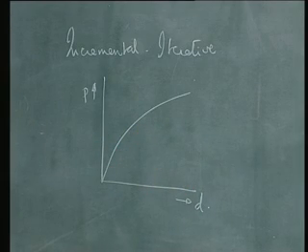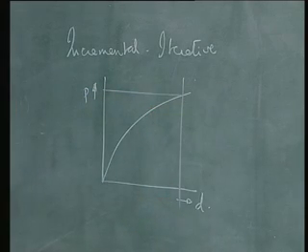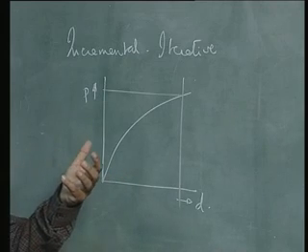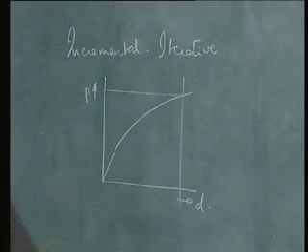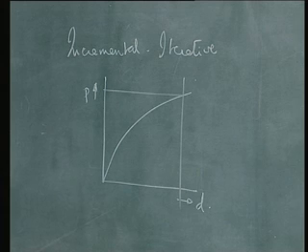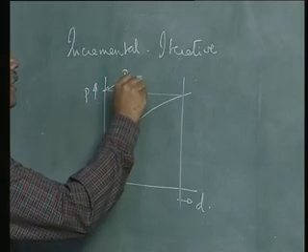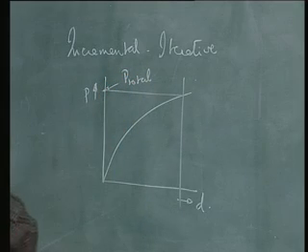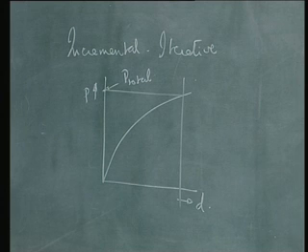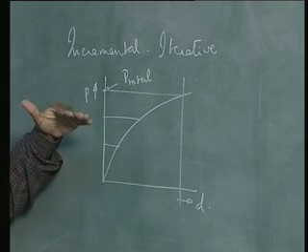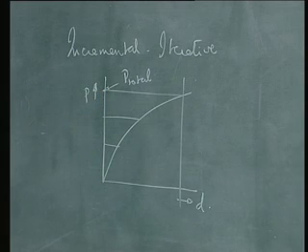So, the whole idea here is, given a P, how do I find the displacement corresponding to this P, so that the load deflection curve automatically says that whatever stresses generate the internal force, that internal force equilibrates this P. Is that right? So, what is it that we essentially do? If this is the total P that I apply, I divide this into smaller incremental loads, say P1, P2 and so on, until I reach the total load, P total.